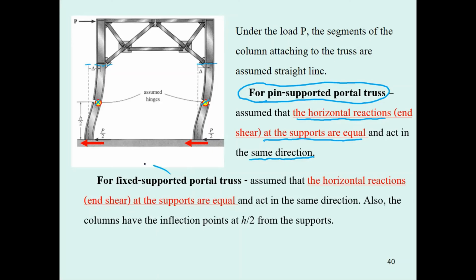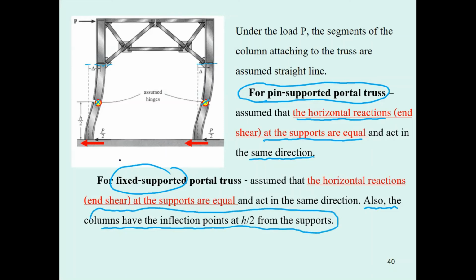If you use a fixed support for this one, you may add more assumptions than with the pin support portal truss, by assuming the inflection point at this location.